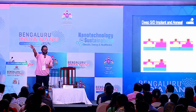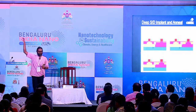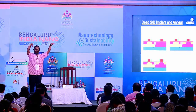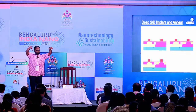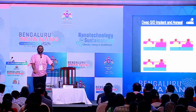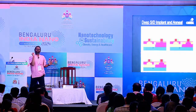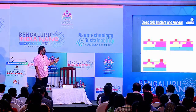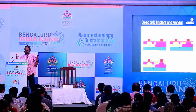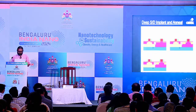Similar to the light that we have here, right? Probably when you go to a buffet, you have these IR lamps. They are basically not for light. They are heating. They are heat sources. That kind of lamp, with very high power, but that will just flash. So that is how you heat it. And when you heat it at that speed, rapid thermal, now the transistor is active, right? So all the dopants are done.